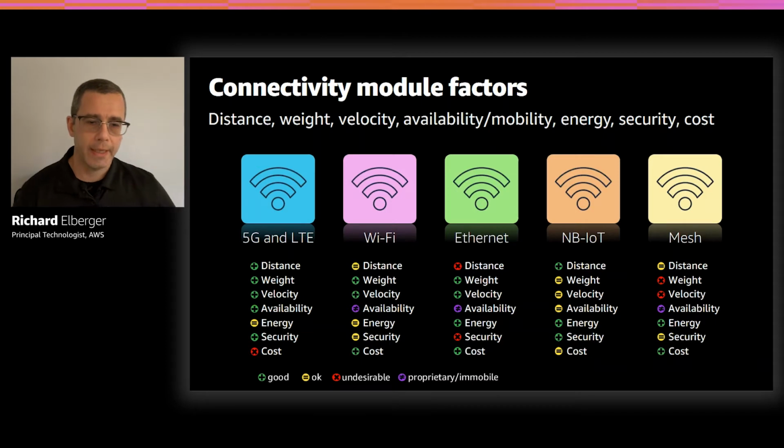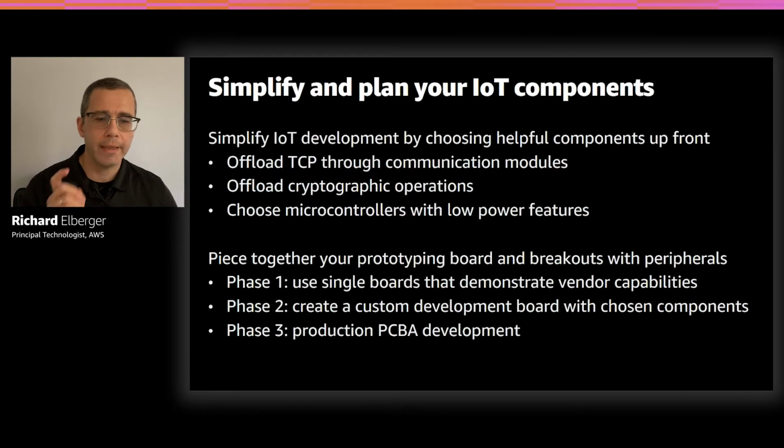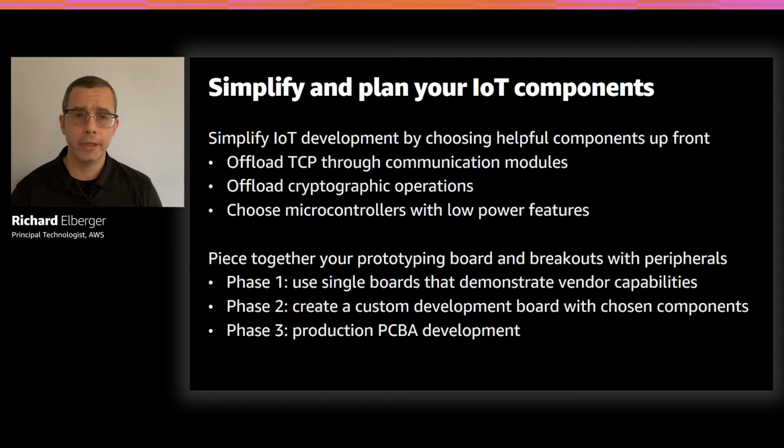So given that, what you already know is, in order to connect to IoT Core, we need to create a secure TLS 1.2 connection, which requires a private key and certificate. Over time, we've narrowed some best practices by working with our customers and partners, especially for the smallest microcontrollers. The choice here is really, really important. TLS is costly from a compute perspective, so you want to be able to offload the crypto operations, all right? Either have the communications module do it, or leverage the secure element or enclave where you can offload the operations.